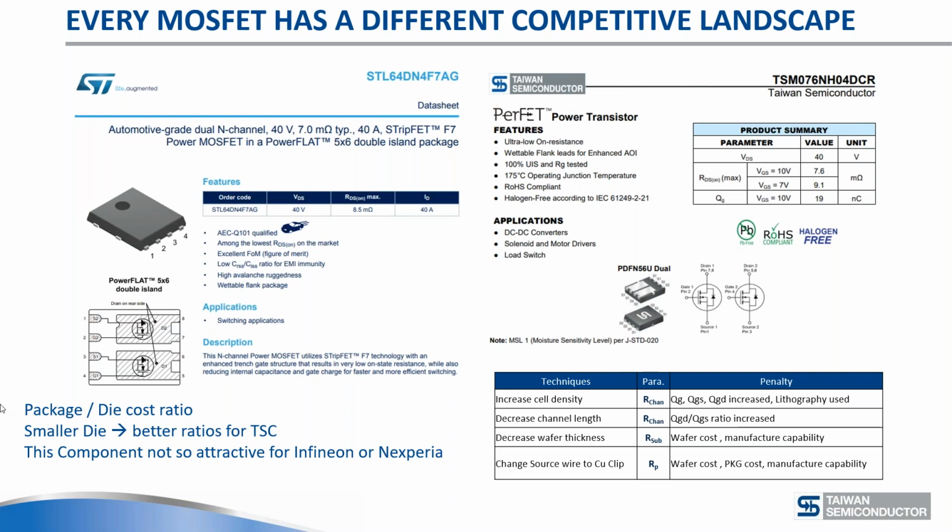And actually here, it is commercially of interest. As we go to 1.9 milliohm, or those big MOSFETs, the ratio of the die cost to the package cost becomes very high. So it's the die that is going to impact the total cost and our competitiveness. With the 7.6 milliohm, even though you have two die, there is a better balance between the package and the die cost.